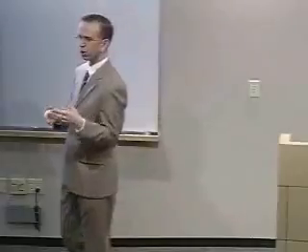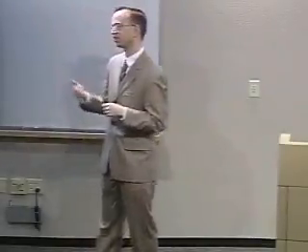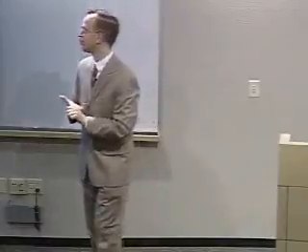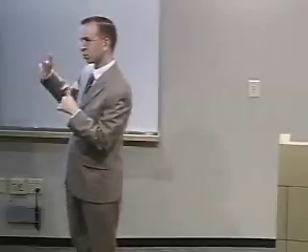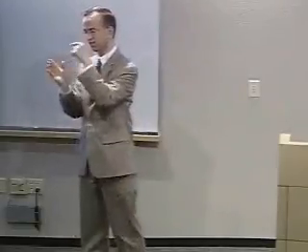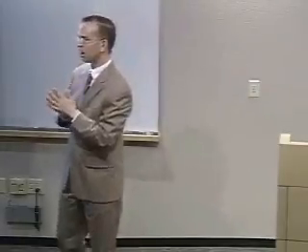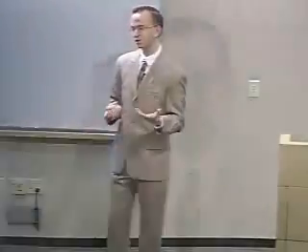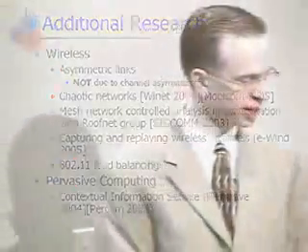It supports a grand total of 8 independent channels, which isn't very many. The maximum network you could do with this channel emulator would be just 3 nodes. And you'd also need some external componentry in addition to do this, because it really just gives you the channel, and it doesn't support, say, a half-duplex node. And the network emulator that I've developed, in contrast, allows up to 232 independent channels. And we directly support commodity wireless LAN devices.